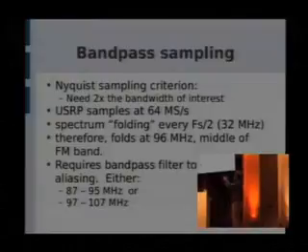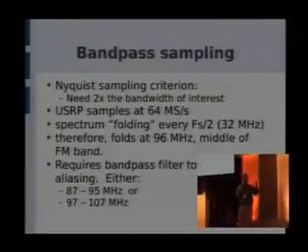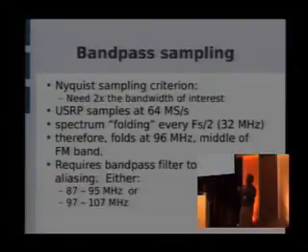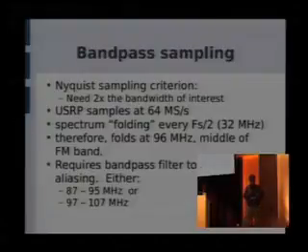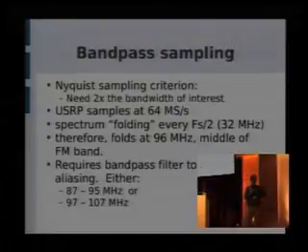So what this is good for in our case is it means that, for sort of regular radio guys, there's no analog mixer in the system. There's no superhet anything. So basically no analog mixer, no analog oscillator, which gets rid of that whole problem, because otherwise you have to figure out how to make that coherent also. So the beauty of this from our point of view is we get the coherency, and all we have to control is the sample clock on the analog to digital converter.